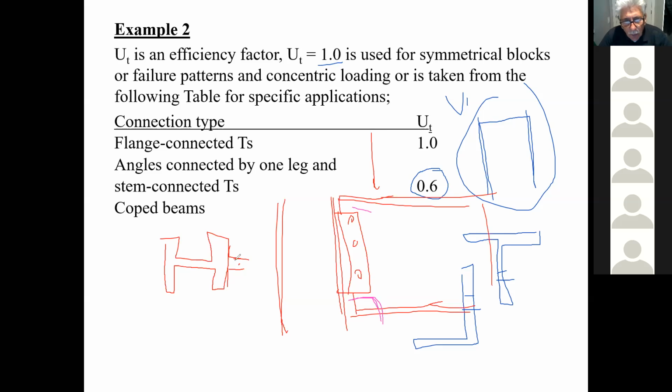So when they're actually erecting this and the crane lowers the beam into this little hole here, it can go through without this interfering to be able to place it correctly. Whenever you have a double angle connection, you always cope your beams if it's going to be dropped between two columns. So that's what they mean by coped beams. And you'll see this a little bit clearer when we actually do the double angle connection in our last lecture, I think. That's when we're going to be doing it.